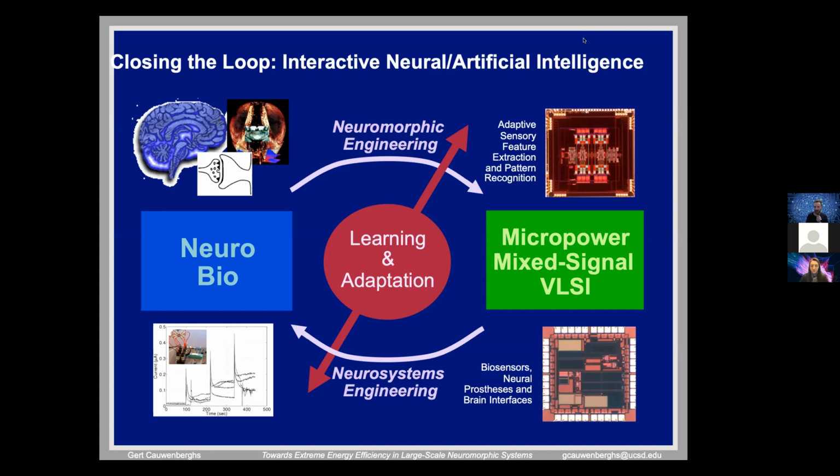And so throughput, in an ideal world, which I think we can get at if we do things correctly, everything will scale linearly with size, with number of elements. So energy is basically a constant cost per operation, but throughput also scales as well. You can take twice more hardware, you get twice more throughput, and that's in the hierarchical event representation that is adhered to. Power and throughput all scale with the number of elements in the system. This assumes that fan out is constant. As long as fan out is constant, this is true. But yeah, it's a great question, Toby. There's much to be done there, absolutely.